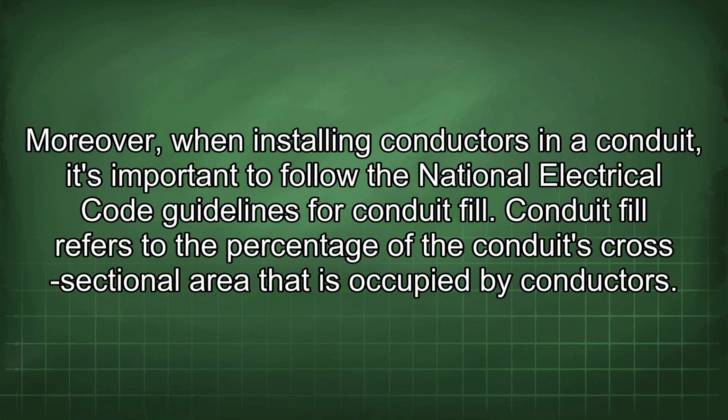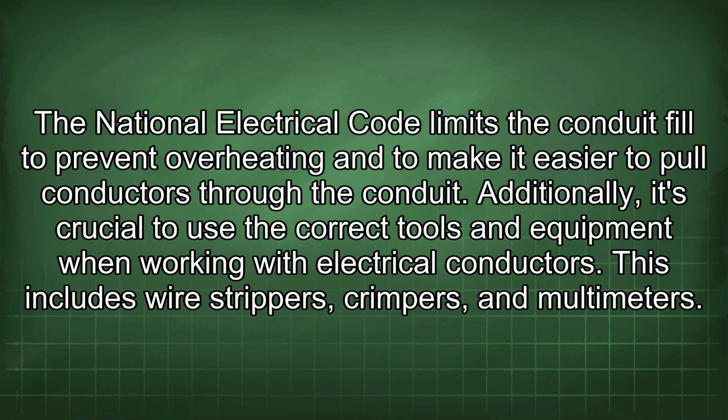Moreover, when installing conductors in a conduit, it's important to follow the National Electrical Code guidelines for conduit fill. Conduit fill refers to the percentage of the conduit's cross-sectional area that is occupied by conductors. The National Electrical Code limits the conduit fill to prevent overheating and to make it easier to pull conductors through the conduit.